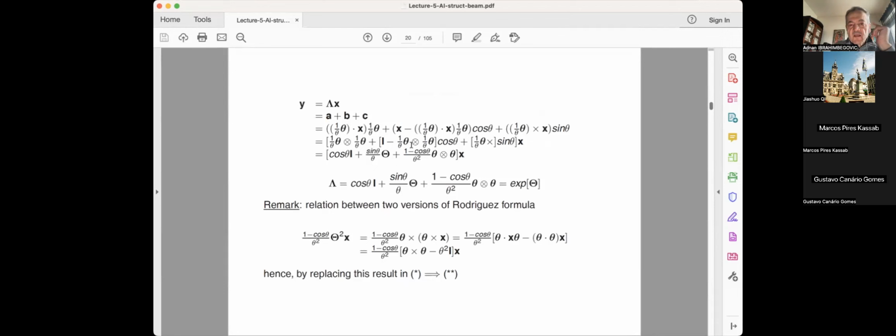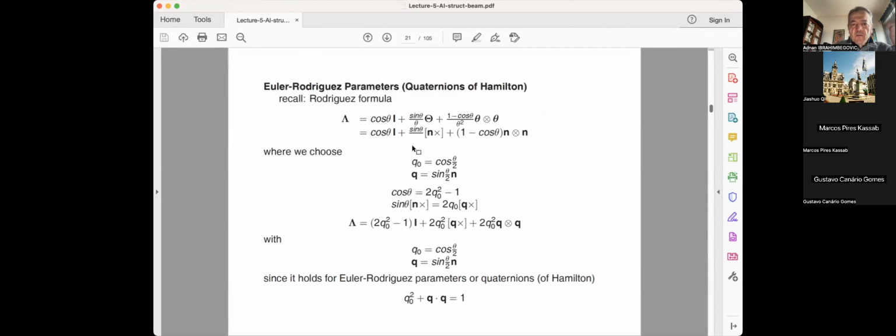Now, if you want to represent a large rotation with 3 parameters, there's already a problem. It turns out that if you really want a unique representation, you don't want to go to the 9 components of lambda, which is a 3 by 3 matrix. The smallest number is 5. This was done in the paper of Stuelpnagel. But in fact, you can also pass with 4.